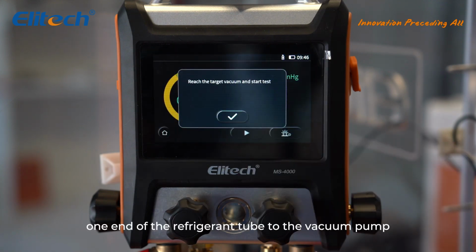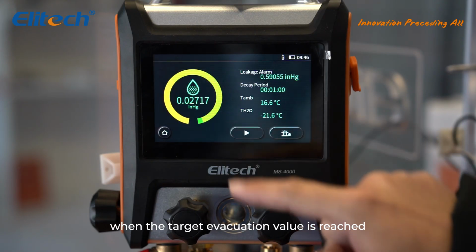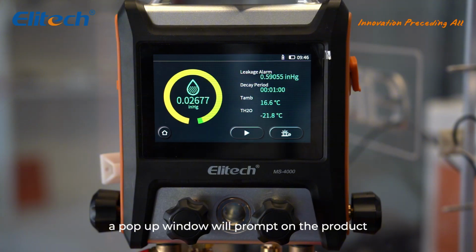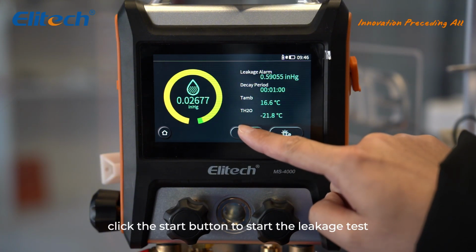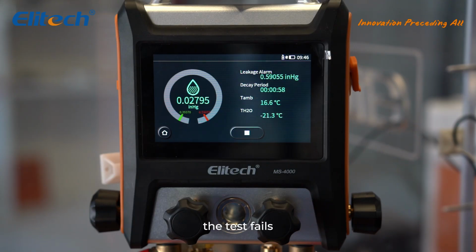Connect one end of the refrigerant tube to the vacuum pump, turn on the vacuum pump, and extract the pressure in the system. When the target evacuation value is reached, a pop-up window will prompt on the product. Start the leakage test. Click the Start button to start the leakage test. If the current vacuum value is greater than the leakage warning value, the test fails.